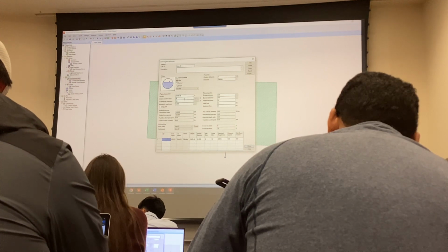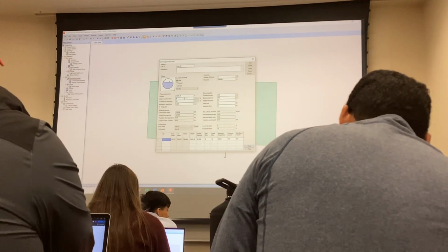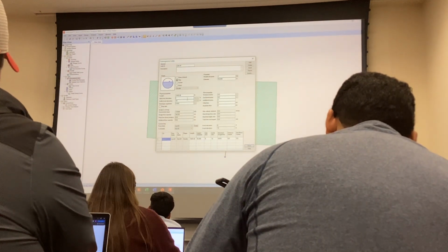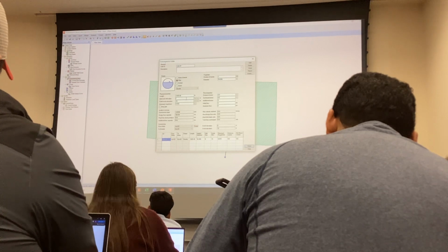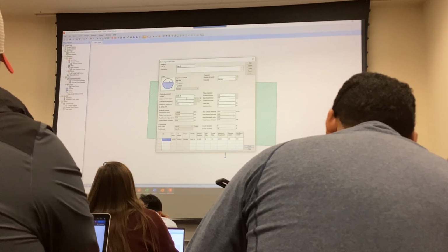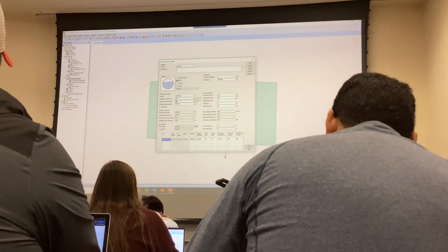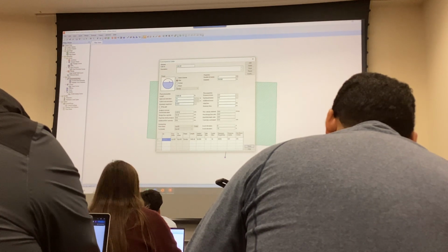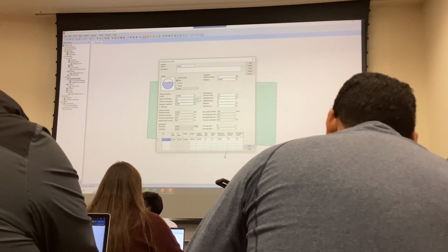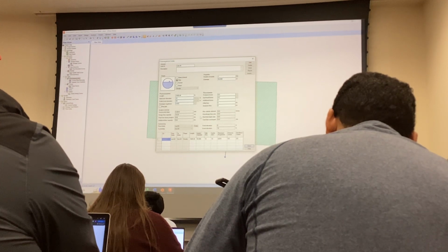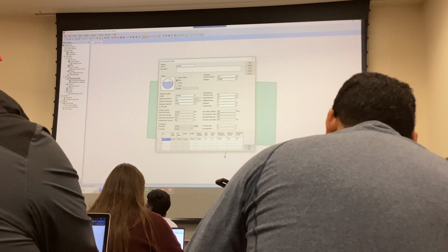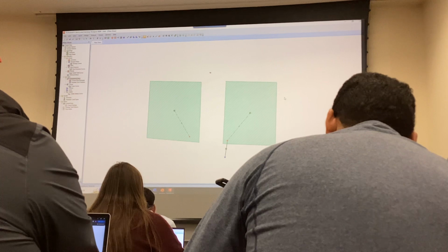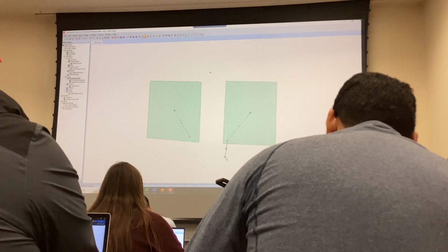All right. So I'm going to make things up. Let's say the inlet invert is 12 feet. Outlet invert is 10 feet, where the bottom of my detention is. Okay, and then I'm okay with everything else. Now I have successfully transferred the water from my junction to my detention.